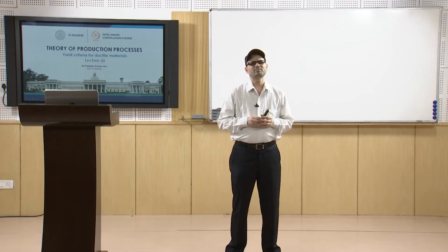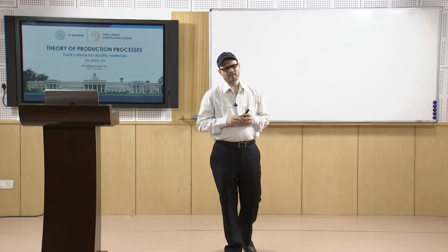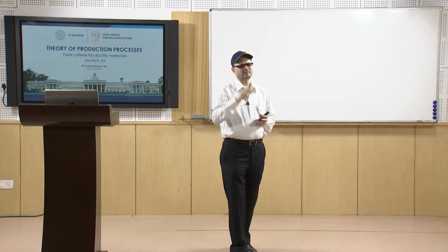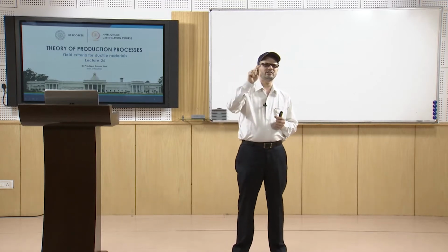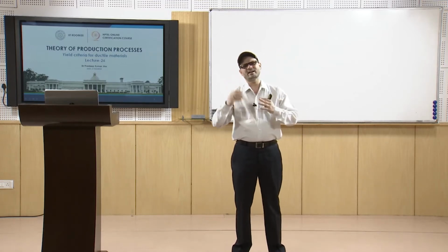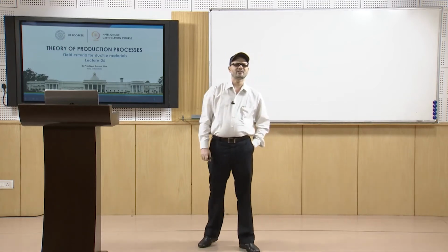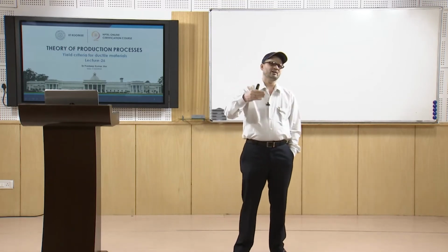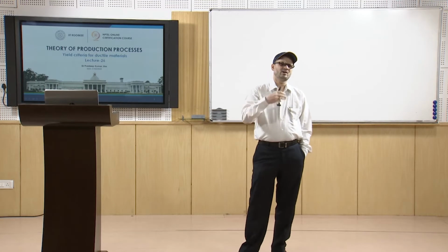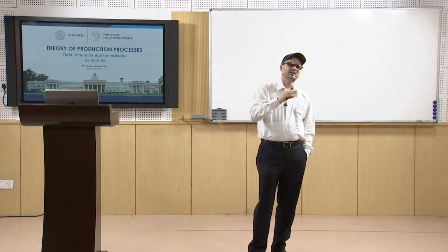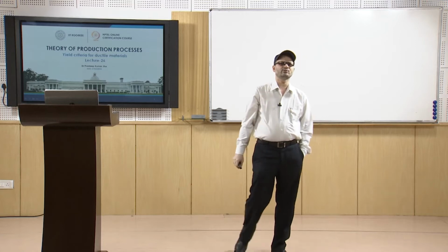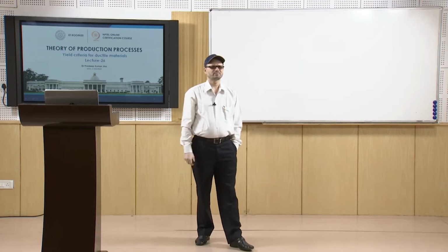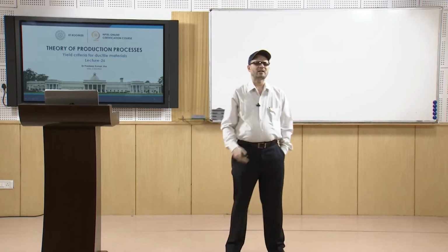At that time the yield stress value is reached. We had seen in the curve that you have a yield stress value, and that is reached. Then onwards we said that yielding has started, and plastic deformation has also started. And if you recall the true stress true strain curve, after that you have a constant increase in the value of true stress because of the strain hardening taking place. Anyway, that we will discuss.